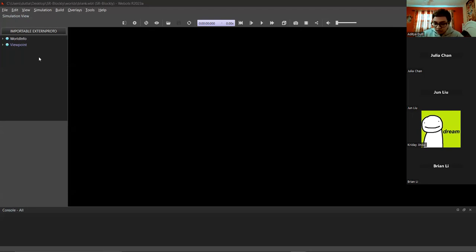The scene tree is where all the elements of your simulation are: your worlds, all your maps, your line tiles, and your robot itself will all be visible in the scene tree. In that scene tree, you'll be able to see their sensors and everything in that. Along the top is probably one of the most important parts of Webots, which shows you how to interact with your simulation. We have a play button here that's used for starting and stopping the simulation.